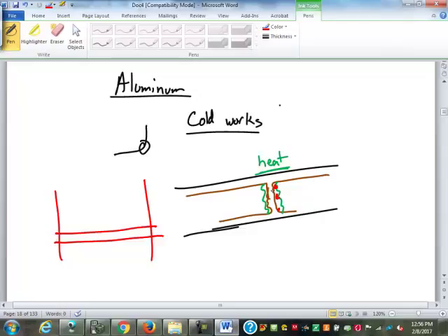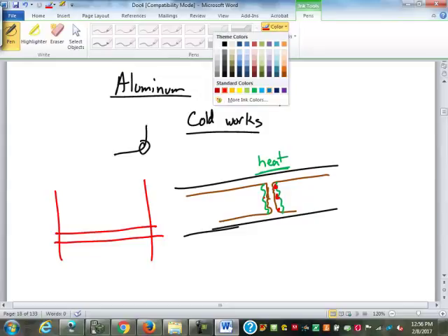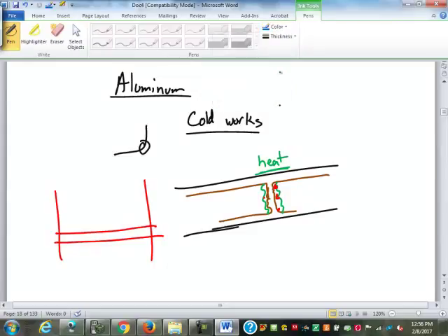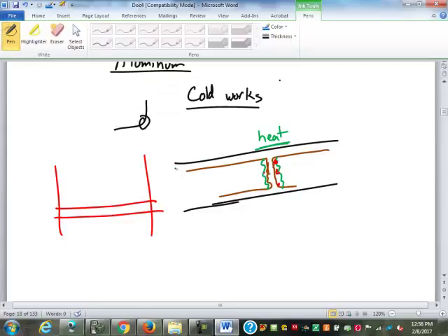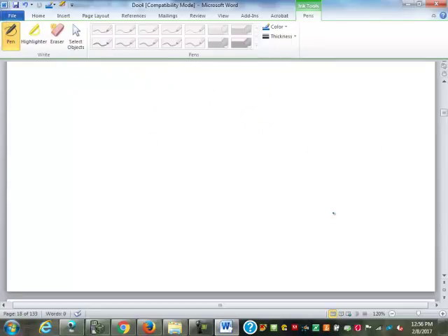Not a fun process. So, moral of the story, aluminum no good. So anyway, one of the ways that we would test is we would go to an outlet where we could pretty accurately figure out how long the wire had to be to get to that outlet. And we would actually test to see what the resistance of that wire was. And from that resistance, we could calculate what type of material that wire had to be.